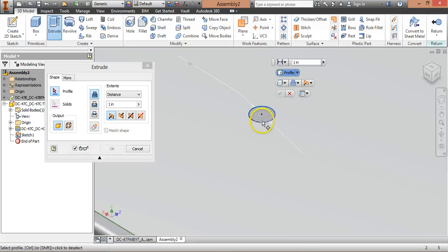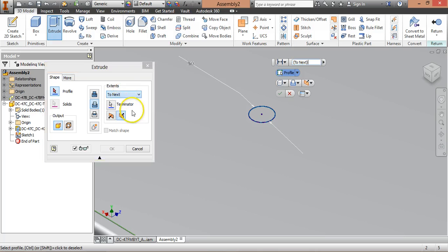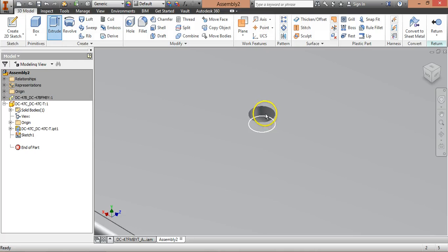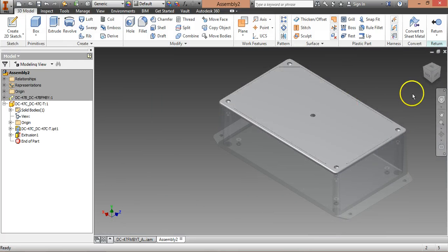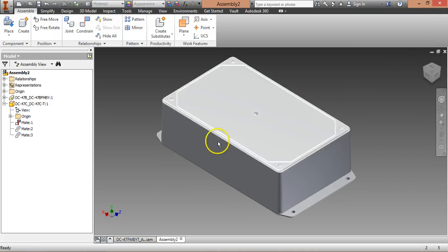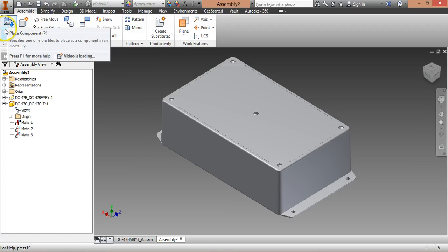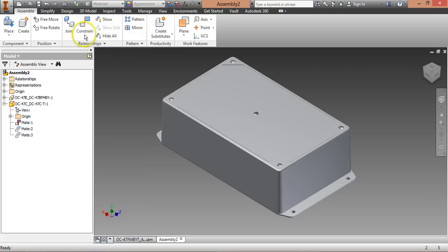I'm going to go here and make an extruded cut in the same way that we always do. Make it 2, next, hit OK, and now we have our cut inside of our part. I can click return, and it will now take us back into the assembly environment which we were just in. So now to import the assembly of the motor and the model of the rotary engine.